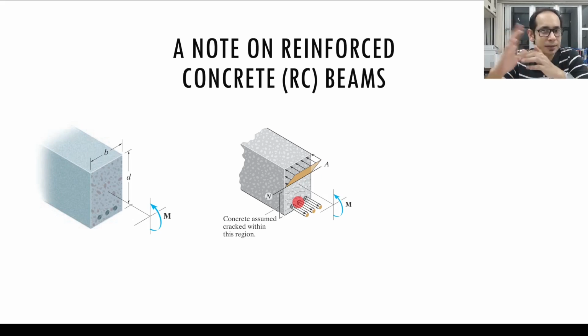Now again, since it's a composite beam, you're talking about two materials, steel maybe with a modulus of elasticity E2, and concrete with a modulus of elasticity E1, right? And as is conventional, like the way we saw in the previous example, we convert the stiffer material into the less stiff material. So essentially you're converting the whole beam into one single material, right?